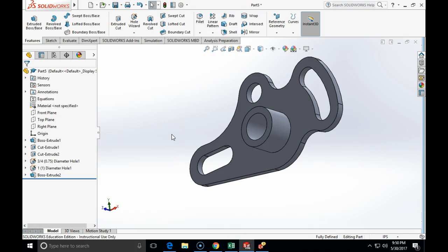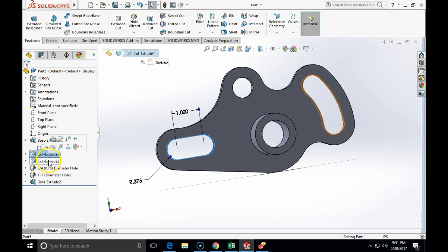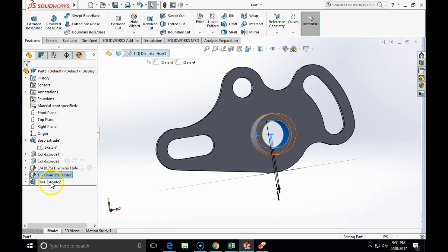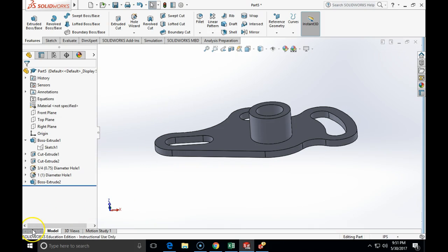So in this demonstration, we've seen how we can create quite complicated geometries using tangential relationships, and how we still keep the minimum amount of information stored in single sketches. If we look at the parametric tree, we created that outside object. We did not trim the circles as we built, but we just were careful to choose all of the areas to extrude. Then we created the slots, and then we created the holes, and finally we extruded the boss around the hole, and this concludes this example.